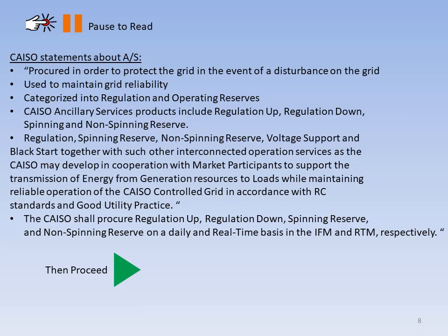Non-spinning reserve is capacity that can be synchronized to the grid and ramped to a specified load within 10 minutes. Other ancillary services such as voltage support and black start are contracted for out of market as needed.